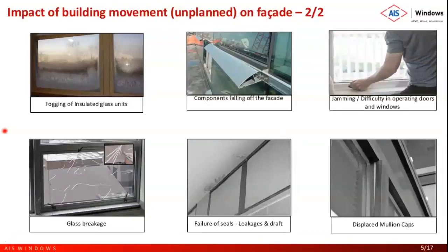That is again because of the fact that when we hand over the structure or hand over the facade to the occupant or to the customer, we try to do it to the highest possible workmanship level, which actually means having all joints hairline, which is actually not correct in most of the cases, but that's how we do it. And as soon as the expansion happens in those components, this component starts getting disengaged. So we will touch upon this in the following slides also.